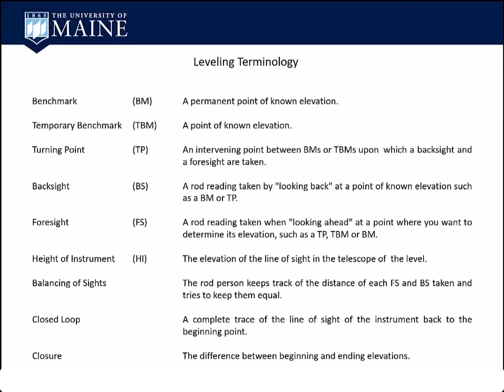Perhaps people that carry elevations, that's fine. Do whatever your boss wants you to. It's his business, it's his license. I just don't carry elevations only because I don't like there to be confusion between adjusted elevations and elevations from the original unadjusted level run.